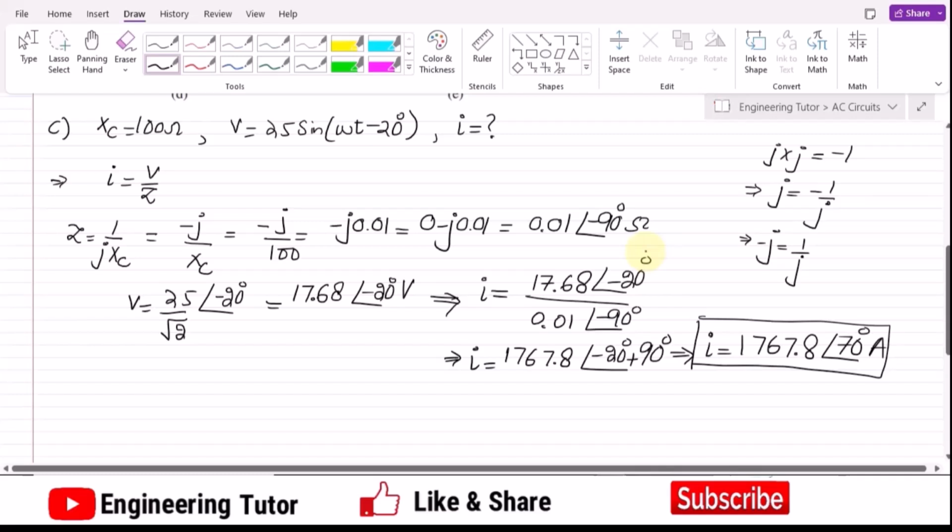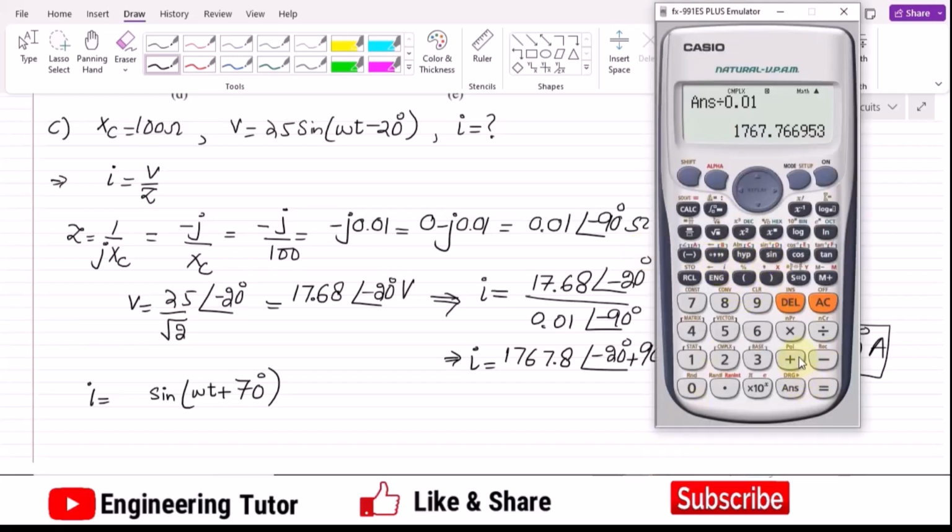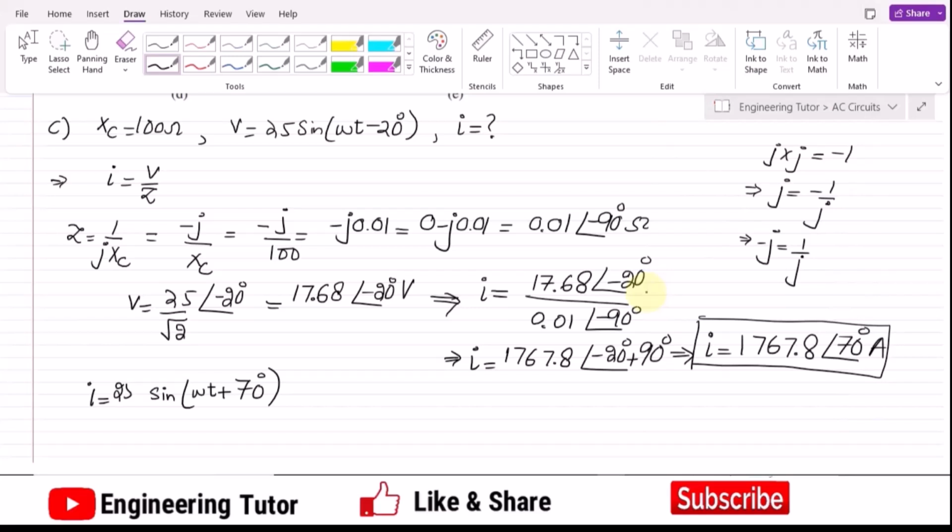In order to convert it into the sinusoidal form, I have to use the same formula, which is sine of omega t, and with it the angle would be 70 degrees. But the value here will be 1767.8 multiplied by the square root of 2. Multiplying it by the square root of 2 gives about 2500. So that is the expression for current.